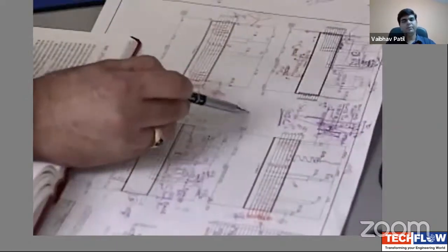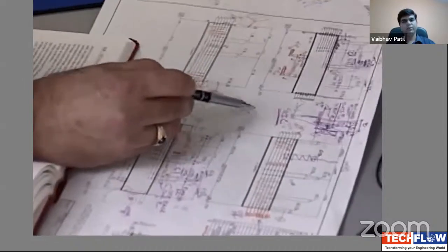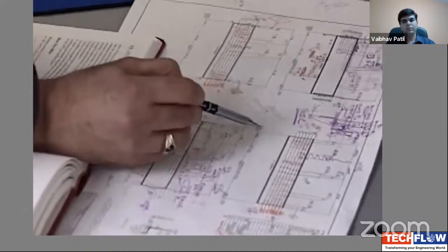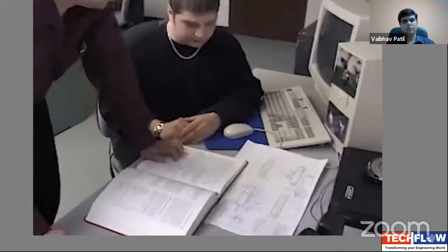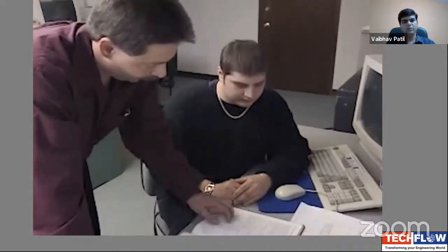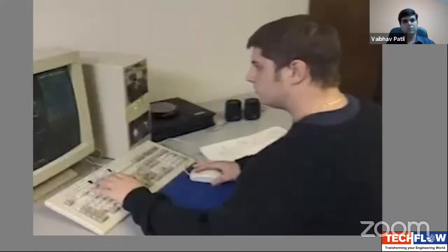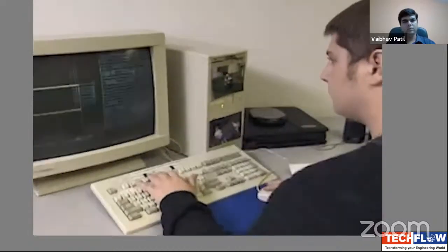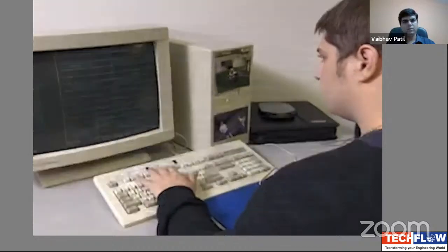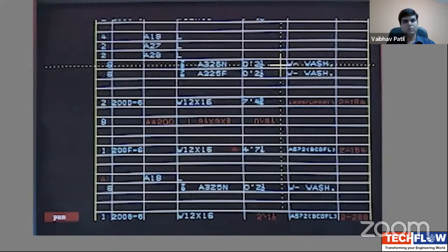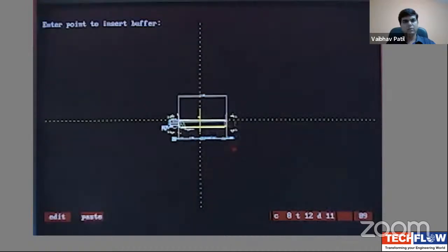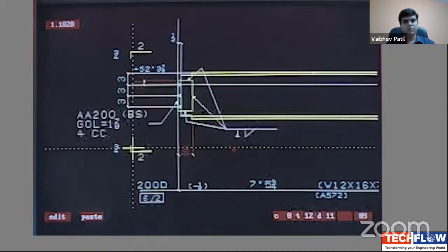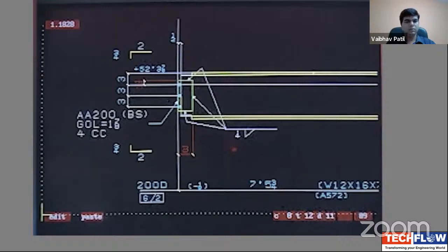To accomplish this formidable task, the detailer will take the design prepared by the structural engineer and, on paper, build a 2-dimension or a 3D model of the steel frame of the building or bridge. It is from this model that the detailer will generate a complete list of every member in the structure, as well as shop drawings for all the individual steel pieces.